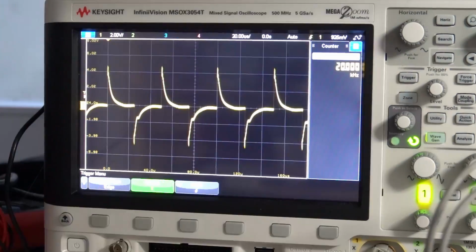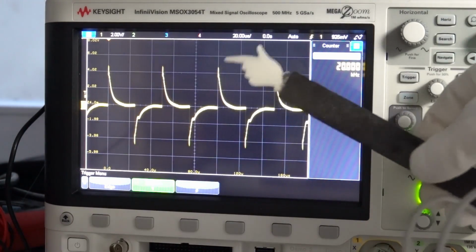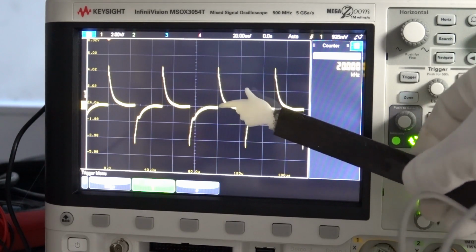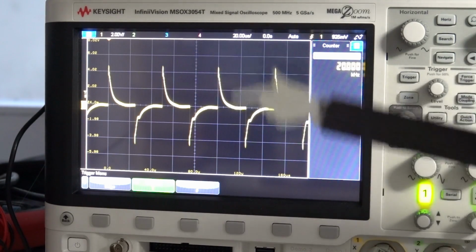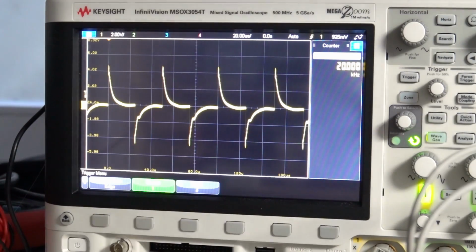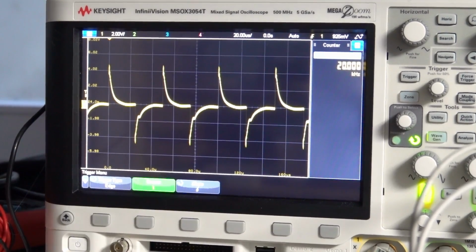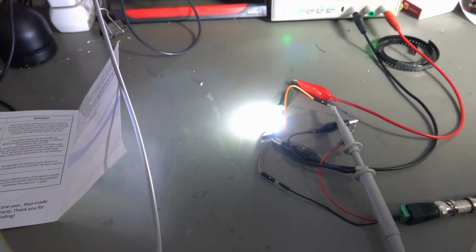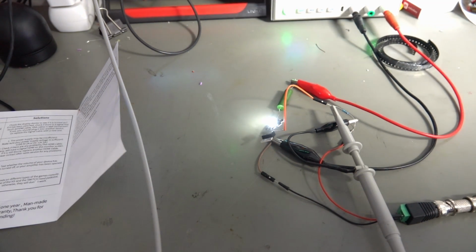from high currents. If we go up with the frequency to, let's say, 20 kHz, we see that most of the time the gate capacity is charged or discharged. This means that the gate voltage is no more digital as we assumed, and the average RDS is much higher than anticipated. And it means that the FET heats up. And as you see here, if we increase the frequency even more, the LED does no more get the full current.